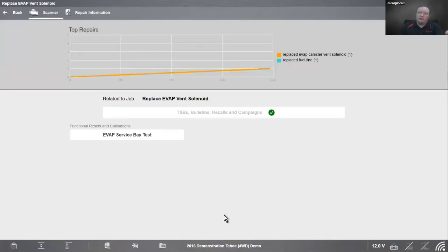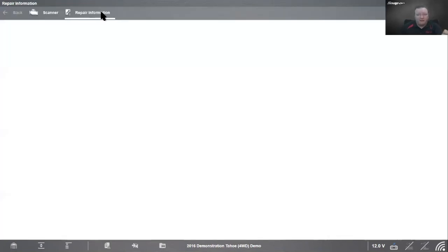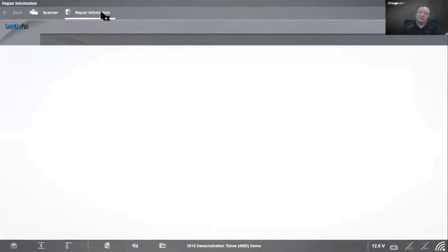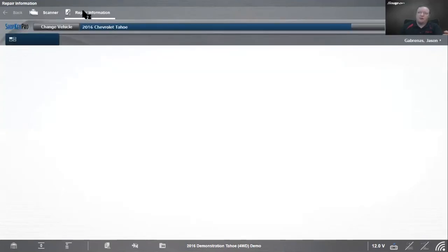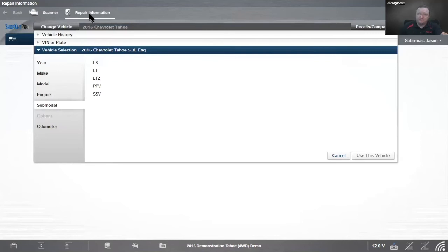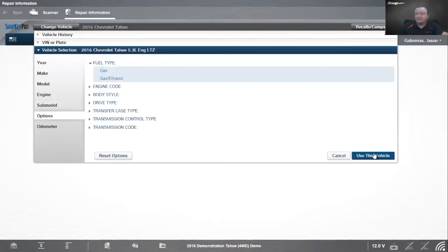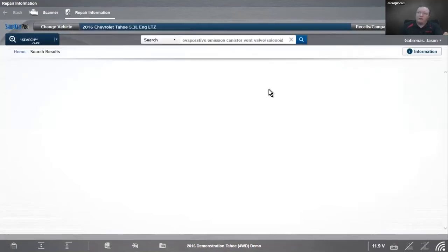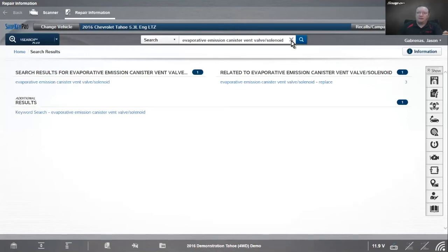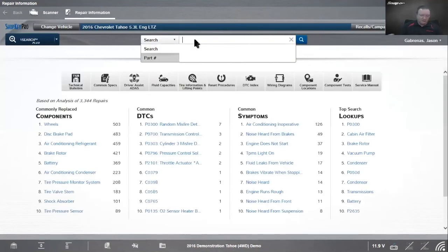This is another one of those tests. If you were here at the very beginning, we had that video, right? So another one of these tests that we need to do to avoid spending a ton of time to set this monitor. So I'm going to go back over to my shop key, into my repair information, and I want to look up the Evap service bay test. So I brought my canister over, so I'm going to go service bay test.